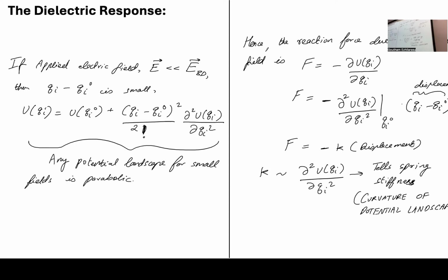Can you explain again what's the KR term? Oh, this is Hooke's law. This is Kx. So this is a spring. Essentially this thing is being modeled as basically a mass with a spring and then a dashpot. What's the difference between the first term and the second? This term and this term. Yes, this is the applied force. This is a responding force, which is the spring trying to compress back. And depending on how fast you move, this is also a responding force. I see. Right? And this is just a force balance. So total force is equal to mass times acceleration.